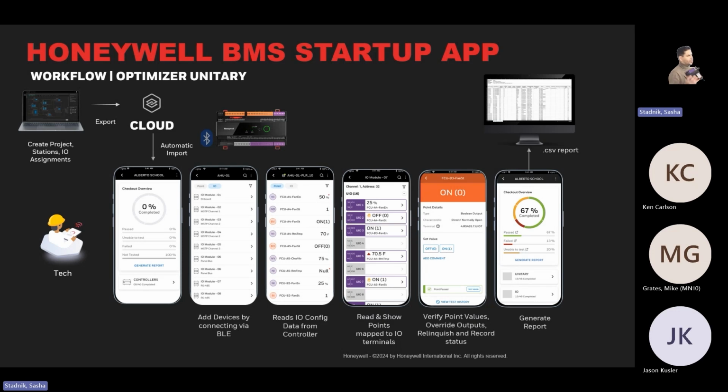Because what happens? Once you have the controllers installed on your site, someone needs to validate that whatever you connect to the controller is actually following the wiring diagram. Because if that doesn't happen, then the sequence of operation and the programming that you have here doesn't work at all. So for many years, in many parts of the world, including the United States, contractors would send the programmer to the site.